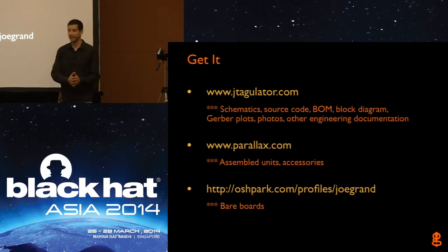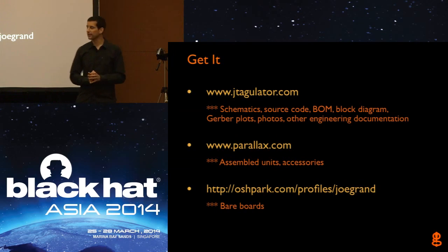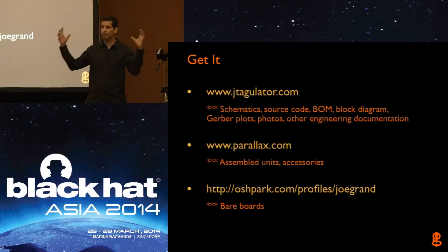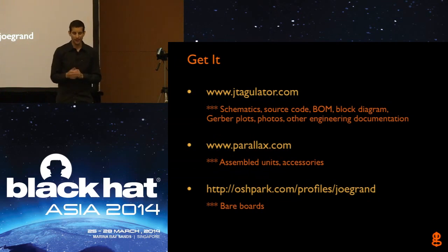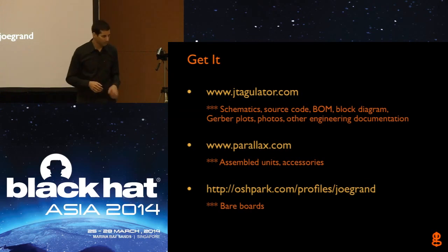OSH Park is a guy out of Portland named Laen, that's his handle, and he fabricates circuit boards for the hobbyist community and basically batches and copies everybody's designs onto a giant circuit board panel and then gets that fabricated, because the cost of board fabrication is really determined by the size of the panel. So if you only have a tiny little part, you might still have to use their minimum panel size. So what he does is batch everything together, and so you wait a few days longer, but now you pay some few dollars per square inch to get your boards back. So I uploaded the designs to there as well, so you can always order from him.